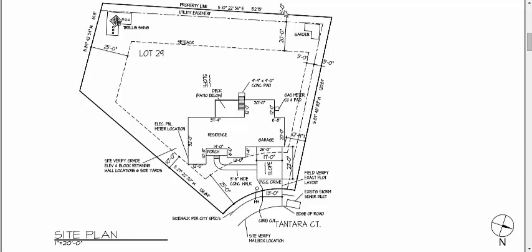So 20 plus 5, right? That's 25 to our lot line. But now there's something called a utility easement. So setback and easement. An easement says that, okay, even if it's in your setback like this, you can't build anything permanent within an easement.